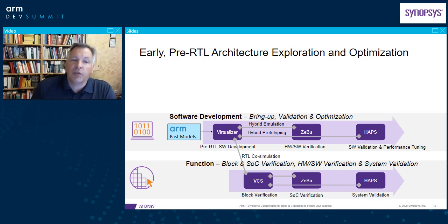So, for example, the aspect of using virtual prototypes for early software development using Virtualizer, or this methodology you can use to develop software early in the design cycle and therefore shift left your design cycle, reduce time to market, reduce costs, increase efficiency. And this flow is using ARM cycle models. And as the name suggests, they are fast, they are instruction accurate, they are functionally accurate, but timing is not modeled in great detail. So thus, they have the right abstraction and speed for this use case.